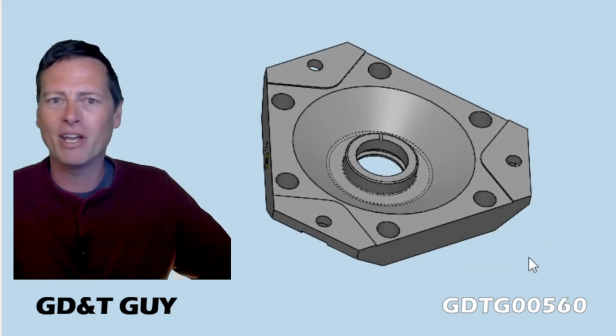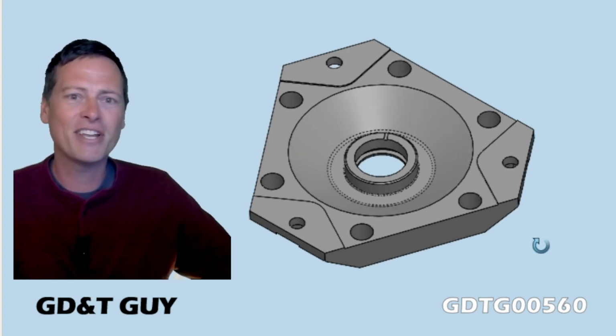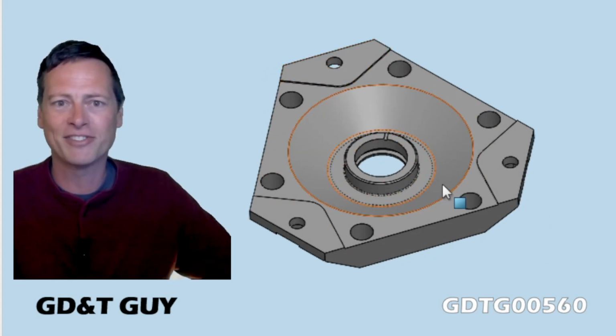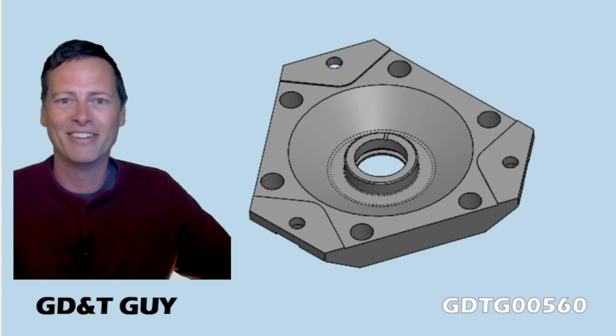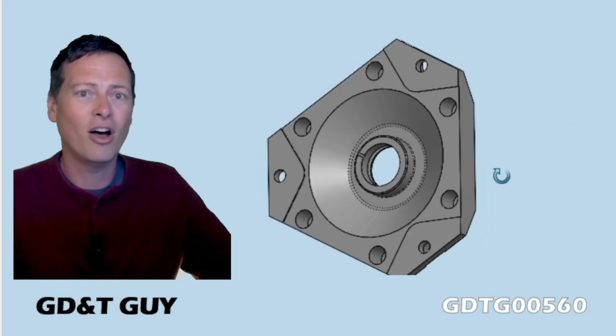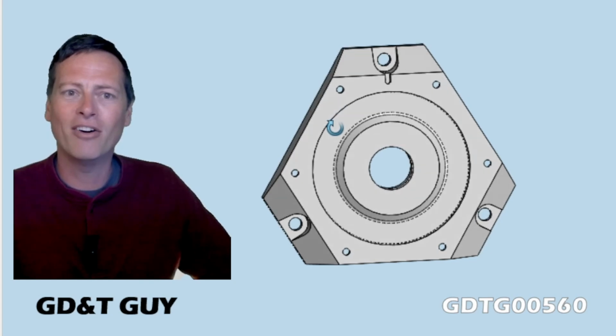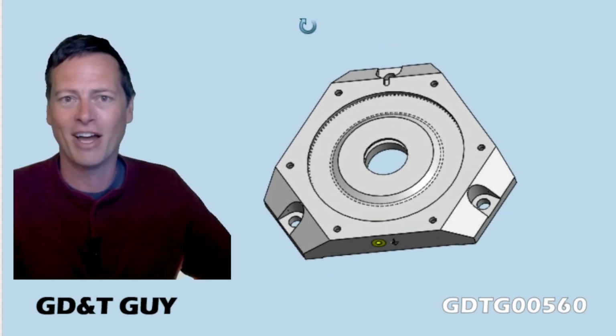This is the base segment of an assembly I'll show you that I'll call the science experiment. And this is going to sit on a table on these 3 flats and possibly get screwed down. There are not really locating features for where this interfaces to the table, although there is lots of other stuff going on with the part, a lot of which is going to fall under the unless otherwise specified profile tolerance. But that's enough for now.